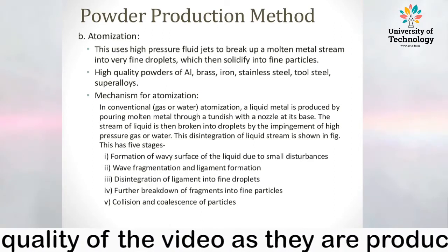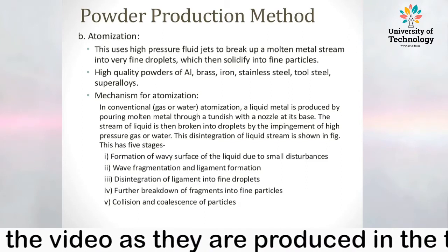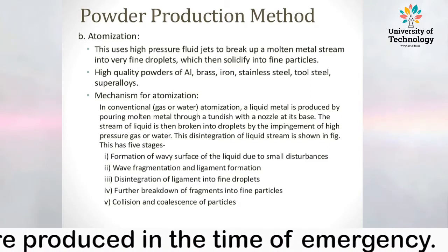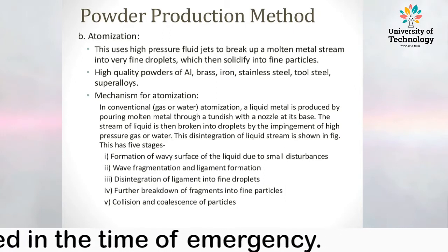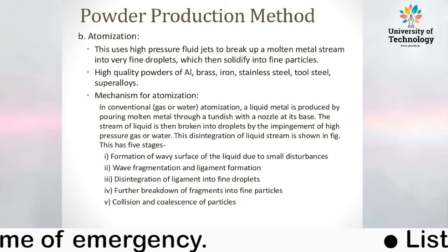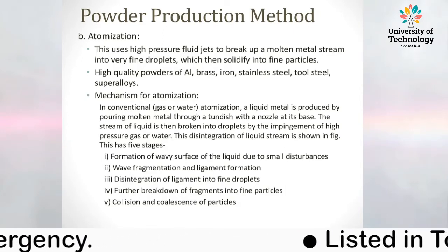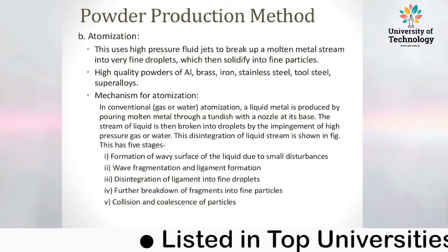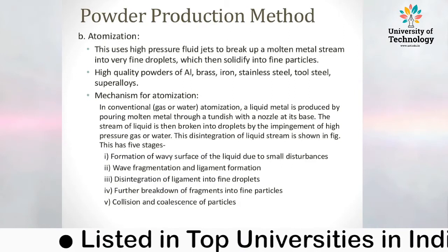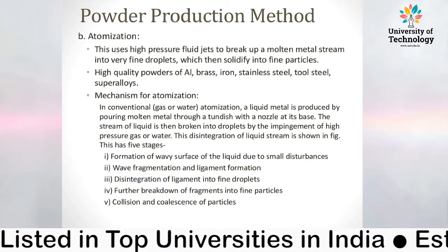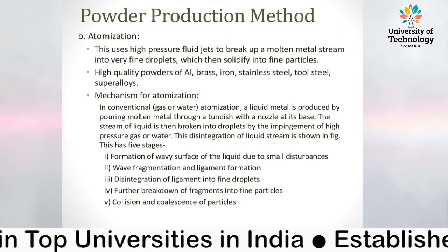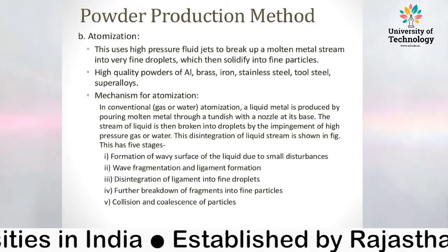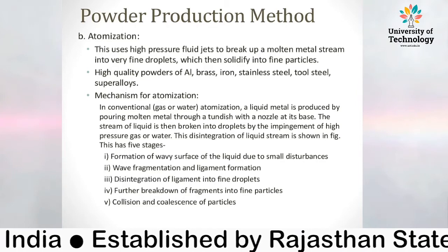The first stage, a formation of wavy surface of liquid due to small disturbances. Second one, wave fragmentation and ligament formation. Third one, disintegration of ligament into fine droplets. Fourth one, further breakdown of fragments into fine particles. And fifth one, collisions of particles.